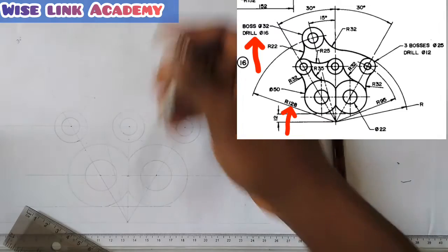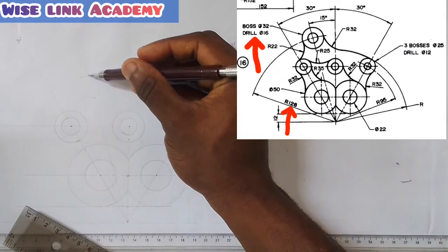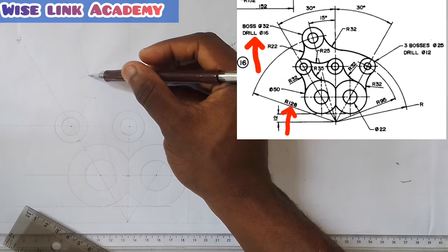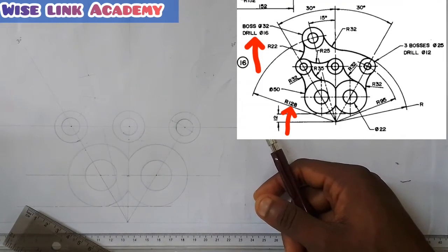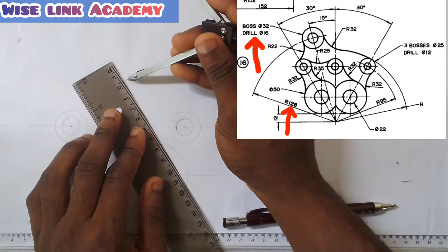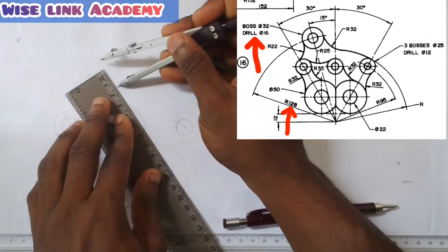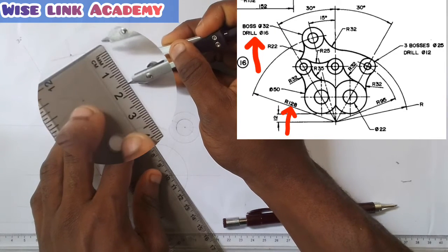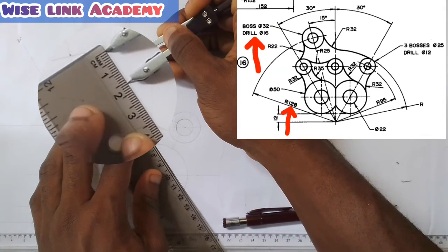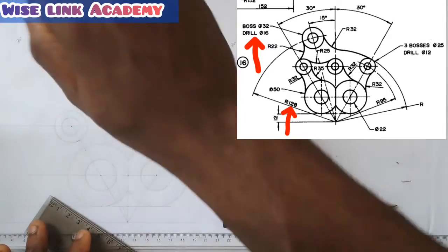Now, where the arc cuts this point is here. That is where that last circle will be. If you observe, that circle is given to be the diameter of 32 and the drill of 16. So 32 divided by 2, I will have 16. So measure 16 from this point here. This 16. At this point here, draw the circle this way.